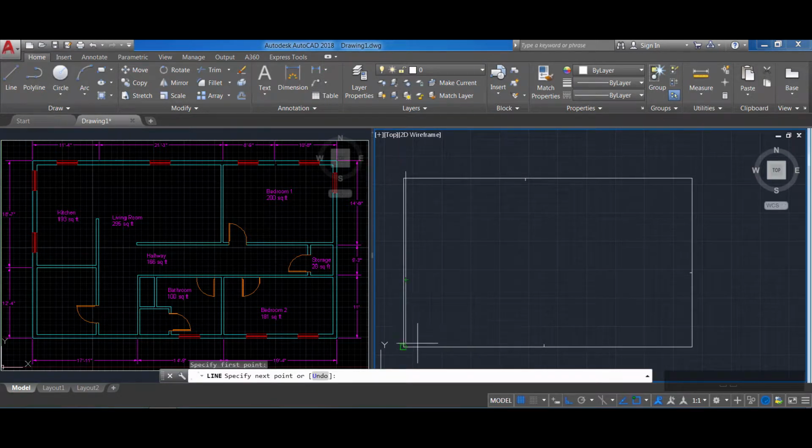Okay, and when I have done that, line command again, and now I'm gonna draw a line here and then another one here using the endpoints, and another line from this endpoint all the way here, spacebar. I'm pressing spacebar to call the line command and to end the line command, so it's really the fastest way to do it. Here, line, spacebar, spacebar again, spacebar. I'm gonna go to my reference point, and here. Okay, we're gonna take care of those extensions there that we need to remove.